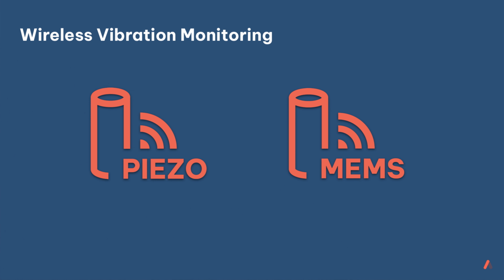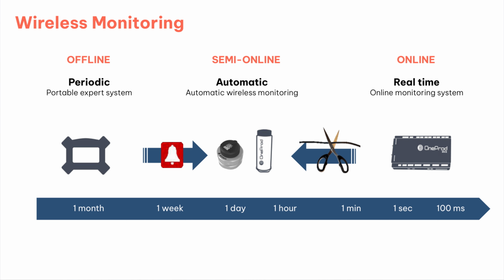So next we're going to talk about wireless vibration monitoring. And this can come in a lot of different shapes and forms. There's piezoelectric and MEMS sensors in this area, and it really covers a lot of your balance of plant pieces of equipment. So wireless vibration monitoring lives in the middle ground, and it's the hot topic these days, but it lives where you need more than periodic walk-around data collection and probably less than a real-time online monitoring system.